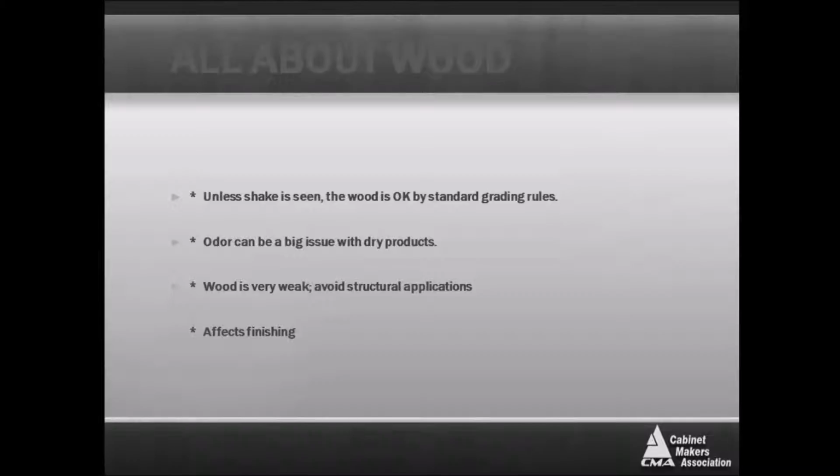And the odor can be a big issue with dry products. When it's wet, you really smell it, but when it's dry, oh man, then's when you get really expensive issues. The wood is very weak. The bacteria have weakened the wood. That's why it splits and gets the shake in it. So we certainly want to avoid structural application.